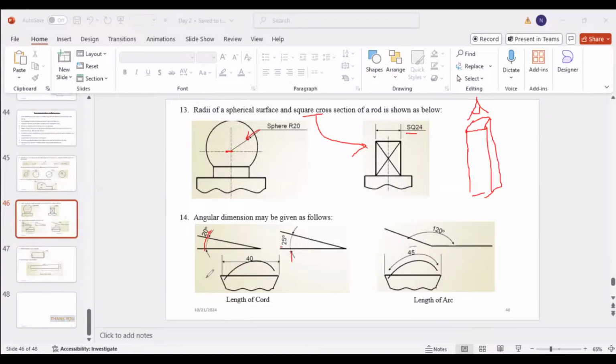I'm sorry. So this here has a curvature surface and a length like this. So this is the length of the chord, meaning from here to here, not the surface length. So here you can see that the curvature length is mentioned using a curved dimension line.